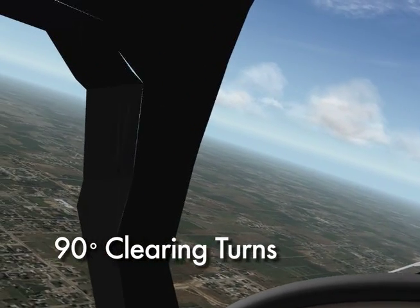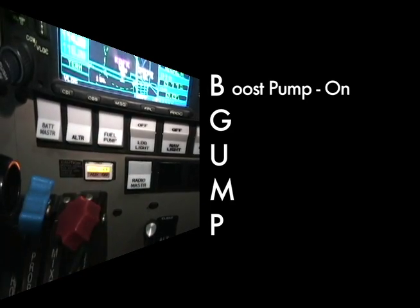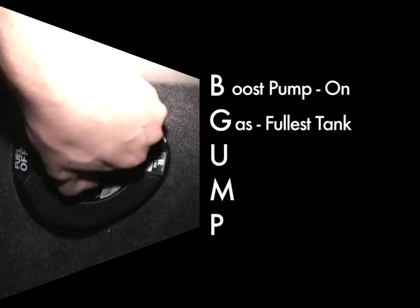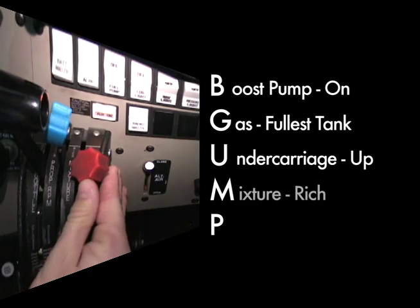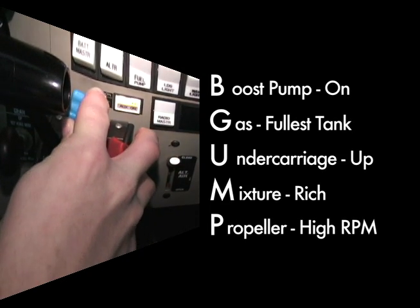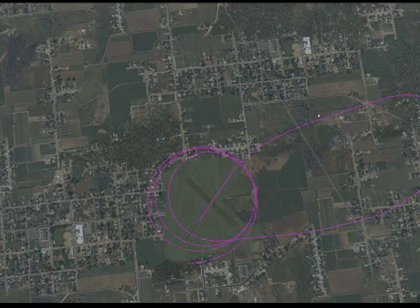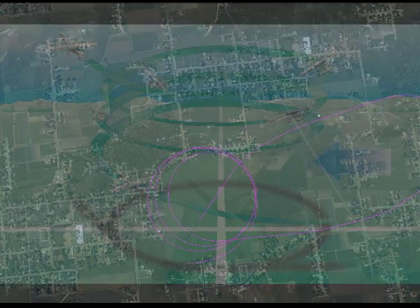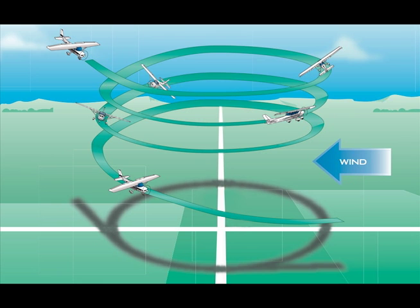For setup, satisfy the B-GUMP acronym by turning the boost pump on, switching gas to the fullest tank, verifying undercarriage up, selecting mixture rich, and by moving the propeller to high RPM. Finally, select a suitable ground reference point. An intersection will work great for a point due to the fact that it is very easy to judge your reference using the extending roads when at high altitudes.